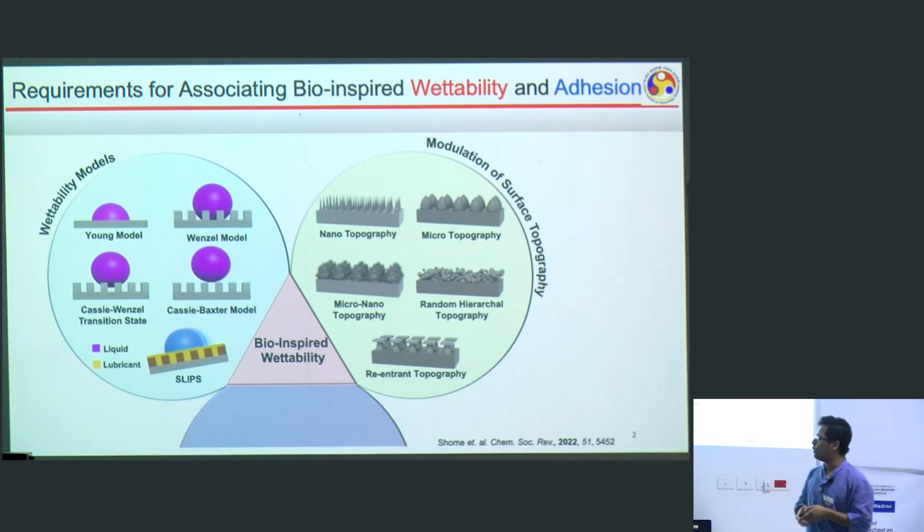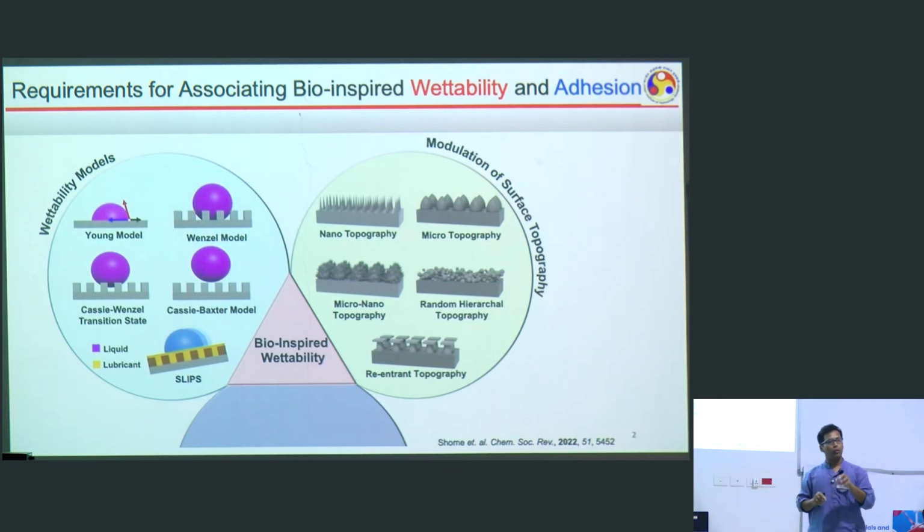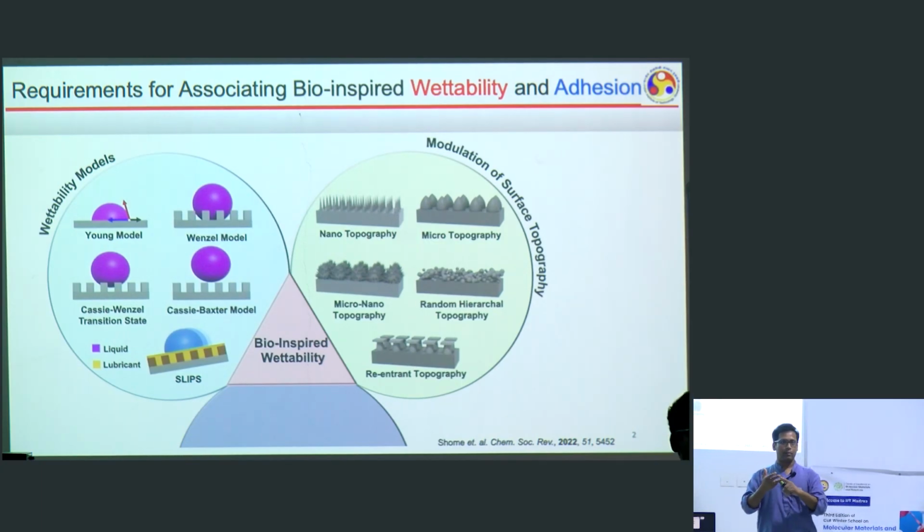When you put a liquid on a solid surface, just imagine this situation where it's a planar smooth interface. You put the liquid. What happened? Three interfacial forces, indicated by red, black, and blue. There are three different forces acting on the droplet. And if you have a 2D projection of this droplet, though it's a 3D object, you will get a unique point on the right-hand side and left-hand side. Those points are called the three-point contact. What are those three phases? Those are liquid, solid, and gas.